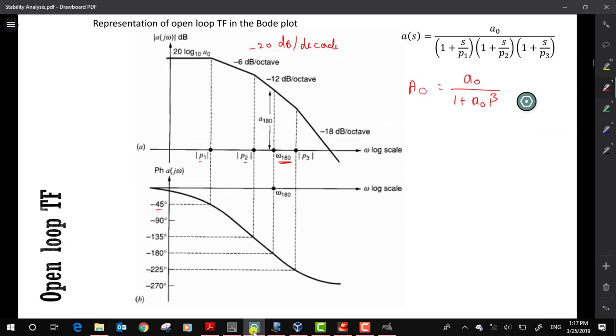Yeah. So now, in the DC conditions, if this loop gain value is much larger than 1, we can do an approximation, right? So what is the approximation that I can do for this A0? 1 by beta. Okay.